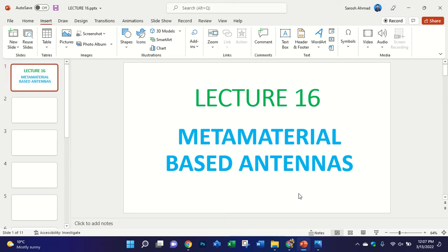Yes, actually, if you are targeting the MIMO antenna, then neglect the single element antenna. Only target the size of the full MIMO antenna. Let's suppose the size of the MIMO antenna is 60 cross 60. You can create a metamaterial of the same size as the MIMO. Even if you want to use the EBG structure, you can place the EBG structure in the center of the MIMO.